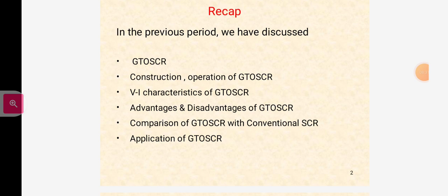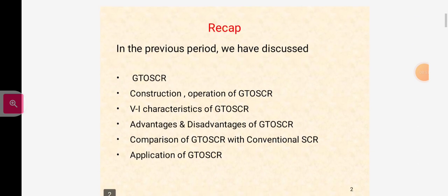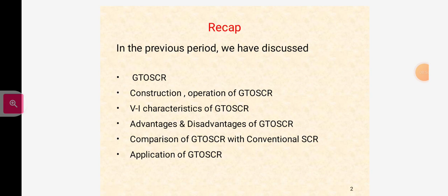an ordinary SCR. In an ordinary thyristor, the current gains of the two transistors NPN and PNP are very high, so the gate sensitivity for turning on the thyristor is high, and hence the on-state voltage drop is low. So here in GTO-SCR, the current gain of the PNP transistor is low, so that turn off is possible if sufficient current is drawn from the gate.